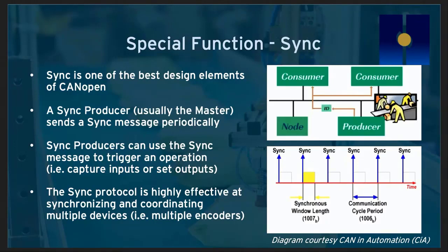As an example, let's say multiple encoders. Let's say you have an application where you want to add half a dozen encoders. That's what you have in your machine, and you'd like an OCS to easily be able to interface with half a dozen controllers. Well, for those of you who use OCS a lot, you know that we can support up to 2 encoder inputs through a hardwired connection with our high-speed counter capability. But if you need more than 2, you need to get a special high-speed coprocessor unit. Well, an alternative to that is to use network-based or CANopen-based encoders. Well, how do you keep them synchronized?